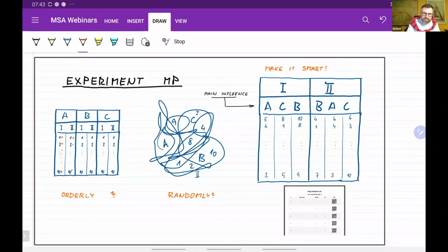If we analyze such data, we need to make some assumptions about the quality of how these data were acquired. And one of these assumptions is the assumption of independence, that each of the measured values is not dependent on the other, as it is in the real measurement process when it measures the production. We really don't know, and it is a work of randomness, what was the part before the one which we are actually measuring. And there is an interaction, an influence between the measured part and what was there before in the measuring device. So statistically speaking, the ideal case would be to collect these values randomly.